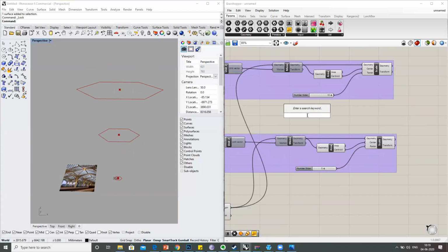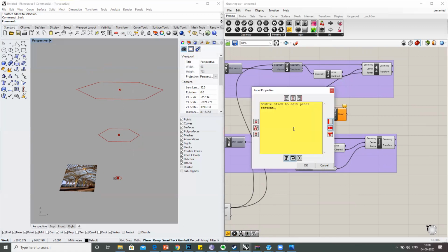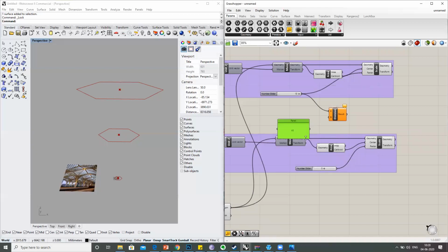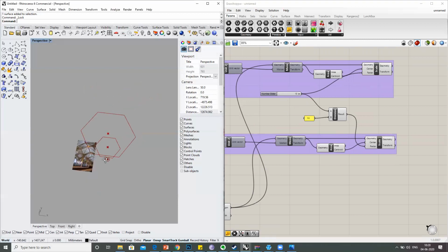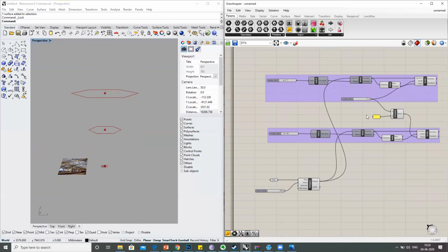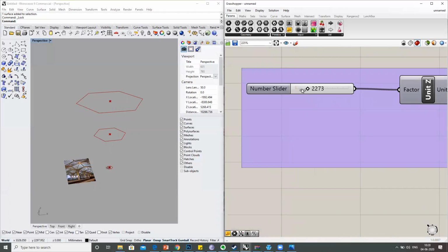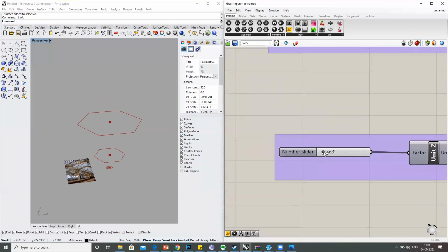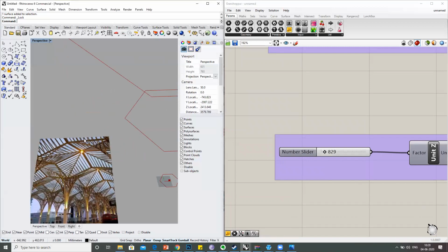So I have this number slider. I can do a division, connect the slider here, have a panel with the value 2, and connect it to this. So this becomes half the previous value. And now just this one number slider will make sure that I control both of them. Good. Now we've done all this. So this is the base, and we've got all this, but let's reduce the height a little bit. Yeah, that seems much more doable.